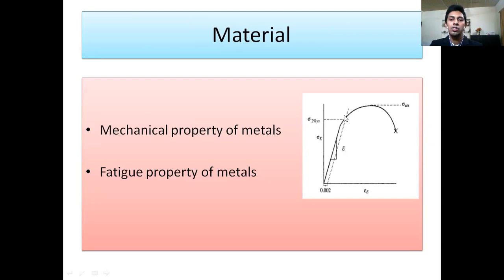A metal consists of metallic atoms that are fixed in a crystal lattice. If we apply a low stress to the lattice, it stretches, and if we relax the stress, the lattice will revert to its original shape. If we reach the yield stress, we will actually break the atomic bonds. This is called plastic deformation, and this is permanent.